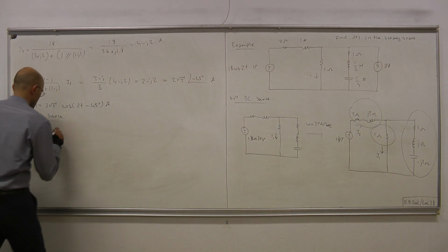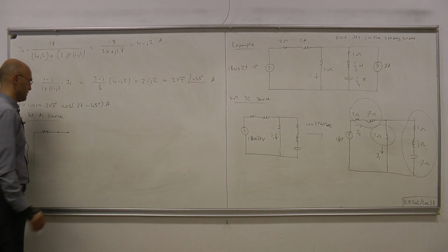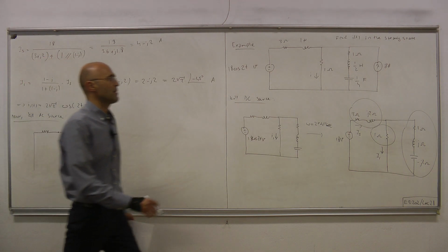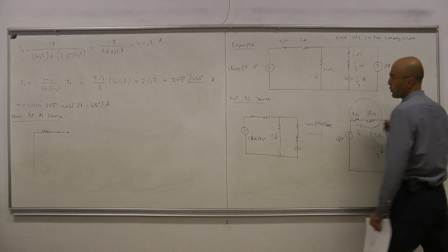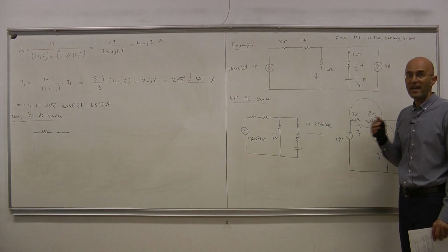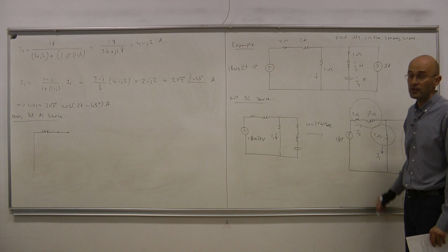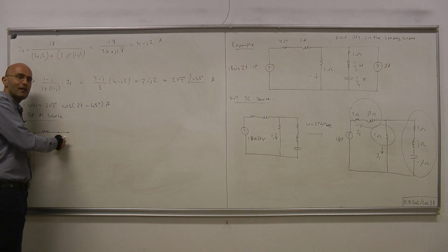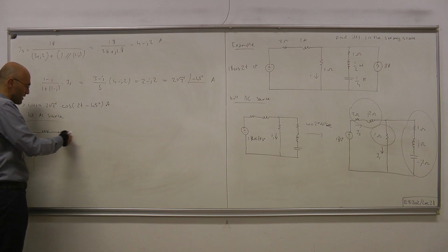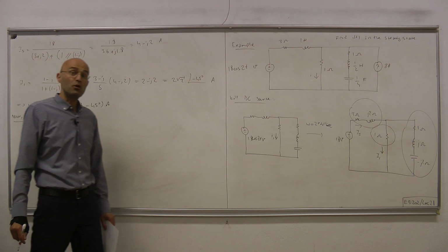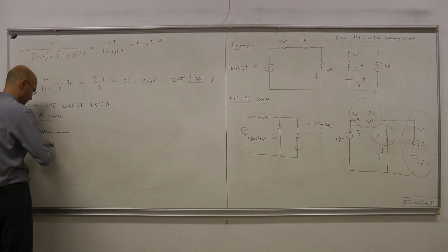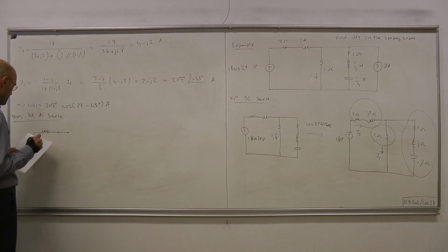And this is our inductor. Or, as we said, from the mathematical point of view, this can be considered as a sinusoidal signal with frequency omega, with frequency 0 radians per second. Again, apply our impedance formula, which is j omega L. Omega is 0, therefore regardless of L, we have 0 ohm impedance, and 0 ohm impedance means simply short circuit. So everything fits nicely together.